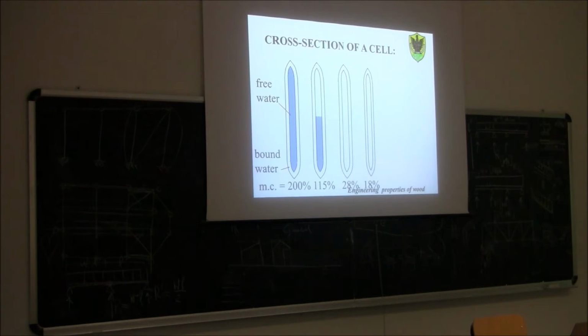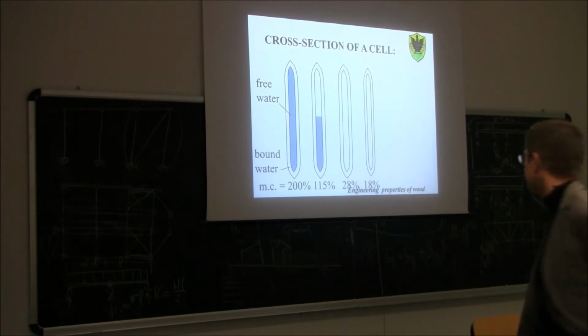So also the bound water is going to be reduced. As you can see here, above the fiber saturation point, since we have just lost the free water, there is no significant change in the size of the cells themselves. So the cells are always the same length and the same width.